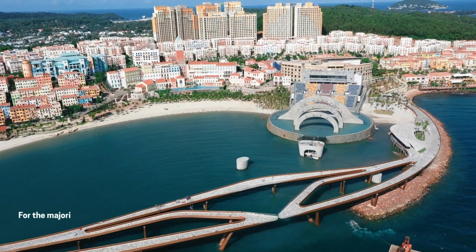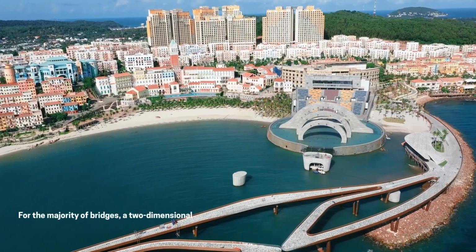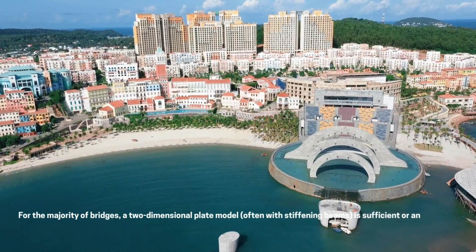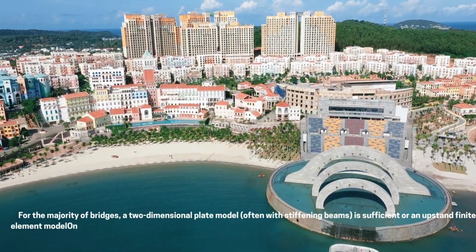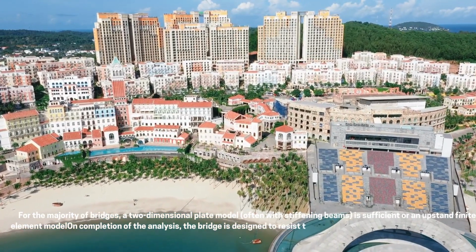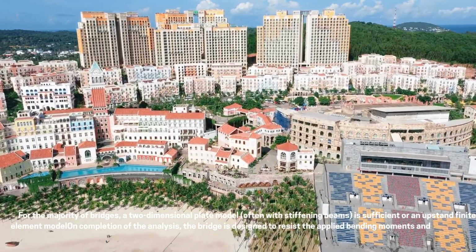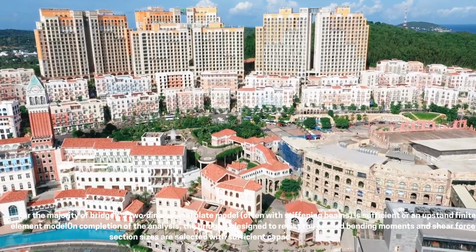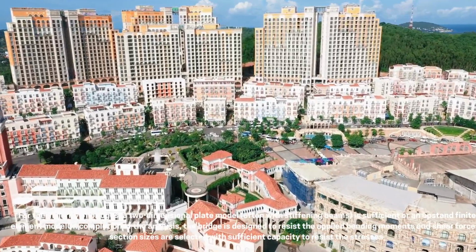The analysis can be 1-, 2-, or 3-dimensional. For the majority of bridges, a 2-dimensional plate model, often with stiffening beams, is sufficient, or an upstand finite element model. On completion of the analysis, the bridge is designed to resist the applied bending moments and shear forces. Section sizes are selected with sufficient capacity to resist the stresses.